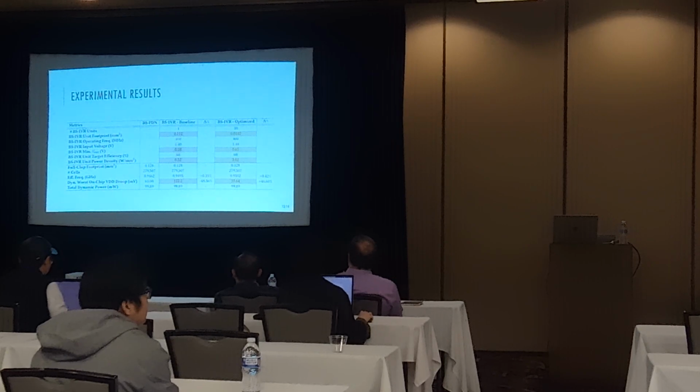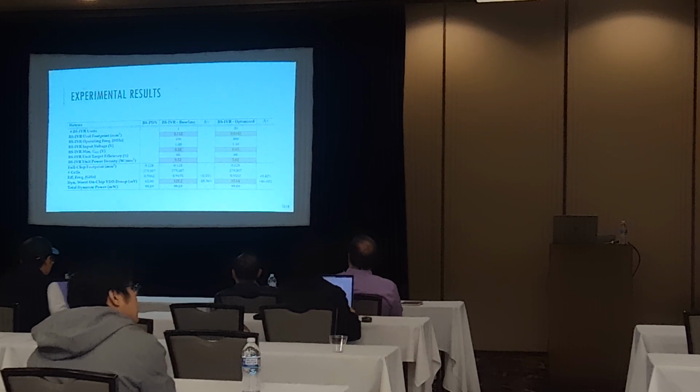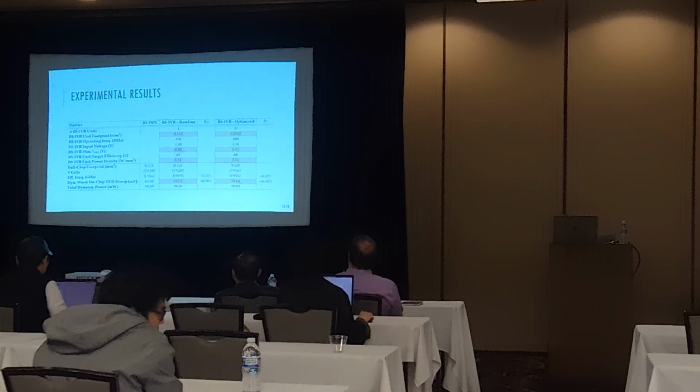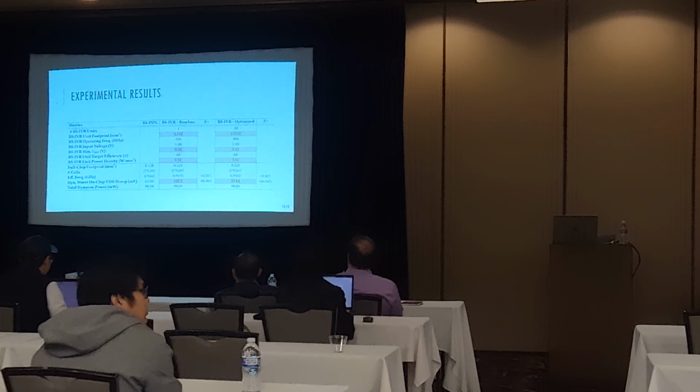So a lot of numbers, but the thing I wanted to show you, first of all, is that our smaller size IVRs are 10 times more than one monolithic one. And then the voltage output is better with 10 small devices working together, 5.8 versus 0.65. And of course, the best result we have on the IR drop itself is with the 10 small IVRs interleaved. We were able to reduce dynamic IR drop quite a bit. So we're very happy.